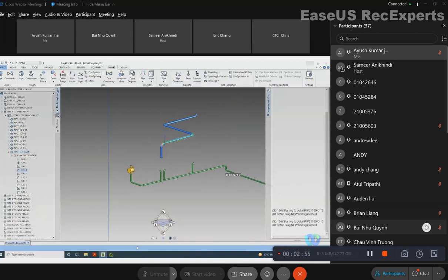For example, this one. What is the spec? SPRE. Spec is A3B. Go to pipe, P spec. This is the attribute. Go to branch, P spec. On that pipe and branch, the attribute is P spec. And on component, it is SPRE.